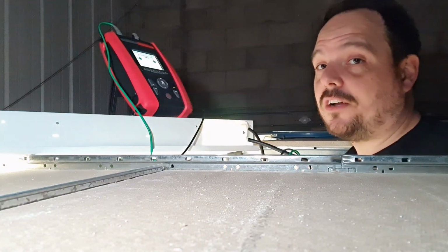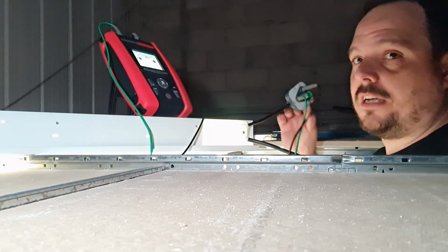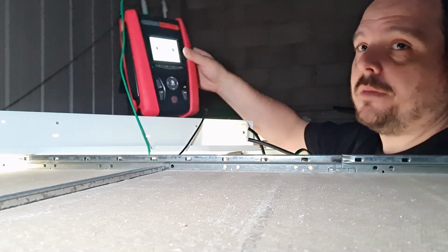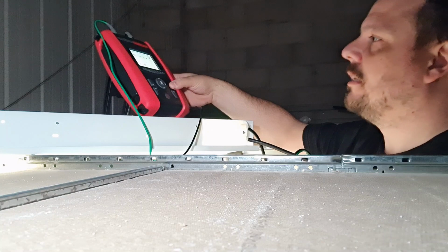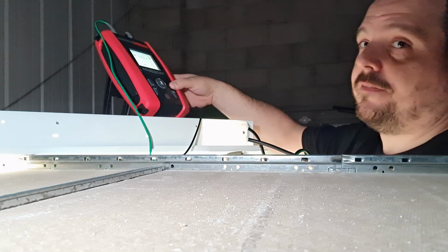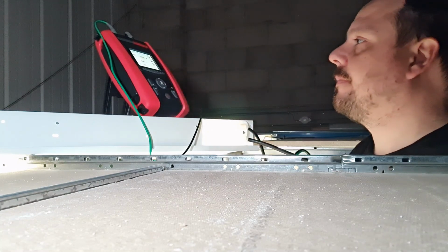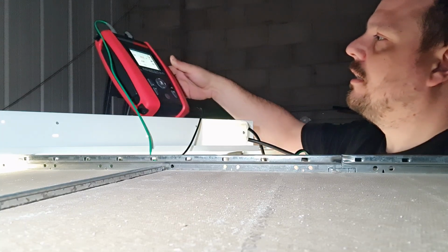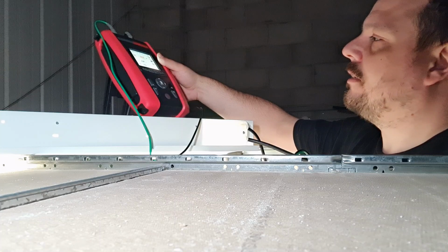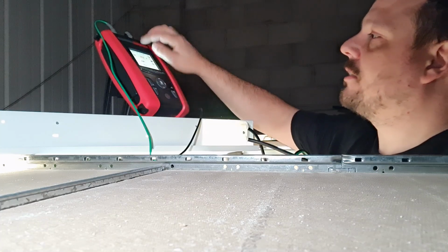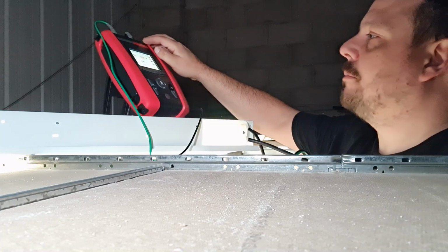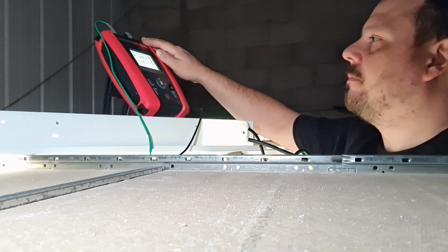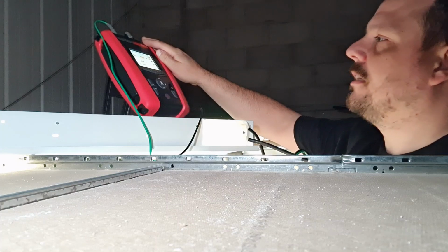Okay, so we've got the power back on now. You can see I'm quite safe. I've got my little test lead in there, wired into the light fitting. I'm measuring 239 volts. I can hit the test button. It's going to give me a value of PFC and also a value of ZS, and you can see I am getting a ZS of 0.56 and a PFC of 0.3 kiloamps, which is sort of what we would expect.